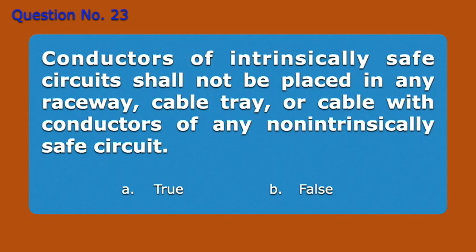Question number 23. Conductors of intrinsically safe circuits shall not be placed in any raceway, cable tray, or cable with conductors of any non-intrinsically safe circuit. A. True. B. False. Answer: A. True.